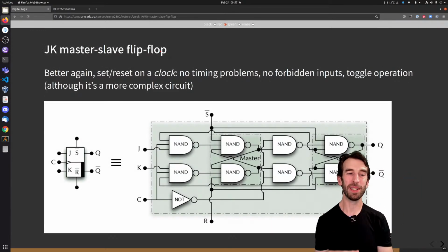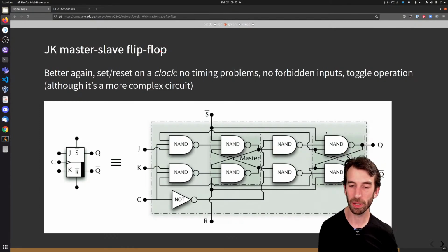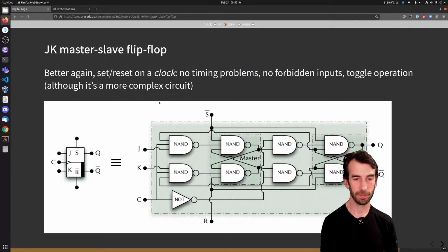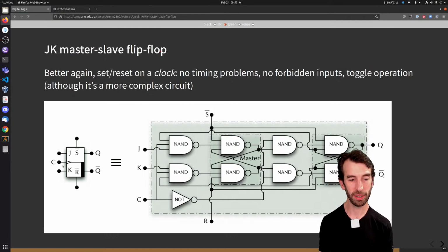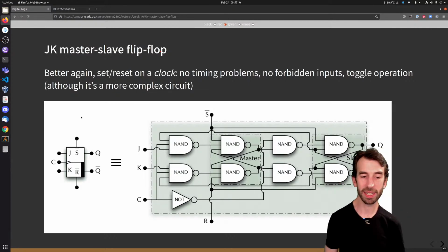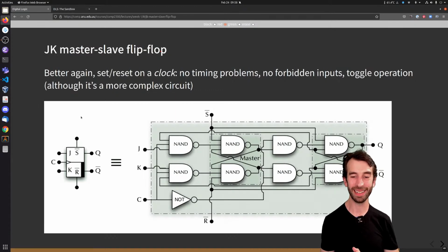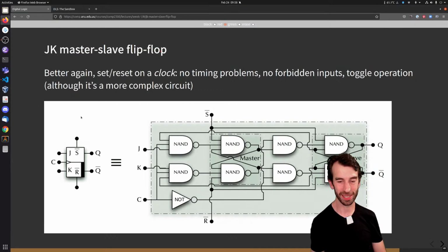Even more complicated one. This one's called a JK flip-flop. And again, there's an SR latch right there, and we've got another SR latch here, so it's a two-SR-latch design. It's giving us a few more inputs and a clock. The idea with the clock is that on a certain change, 0 to 1, it would allow you to set the latch. I haven't actually tried this one in DLS, but maybe we should make it and have a try. I might have a try after the lecture, if anyone is still around.